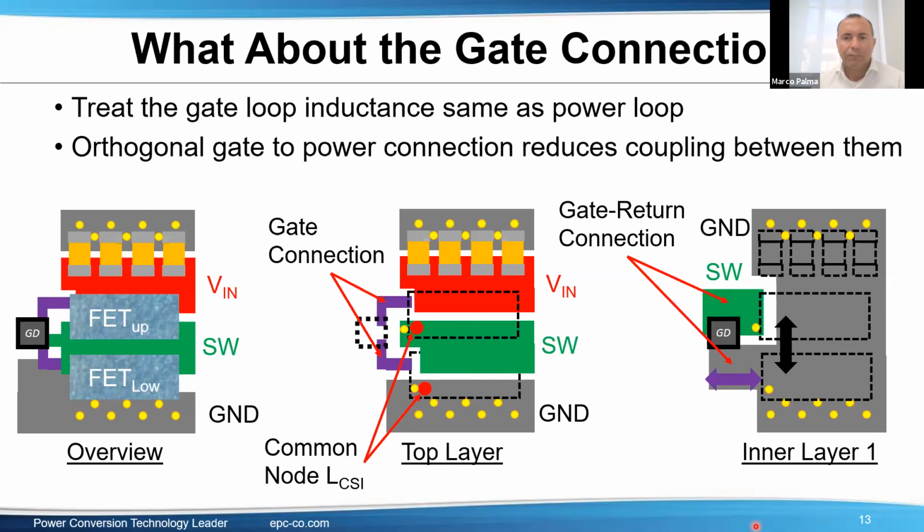Okay. For the rectifier FET, having higher gate loop inductance makes it difficult to keep the FET off in case of SW transition, for example, when the SW flies up in the case of a buck. How is this solved if the gate loop is optimized for only the control FET?